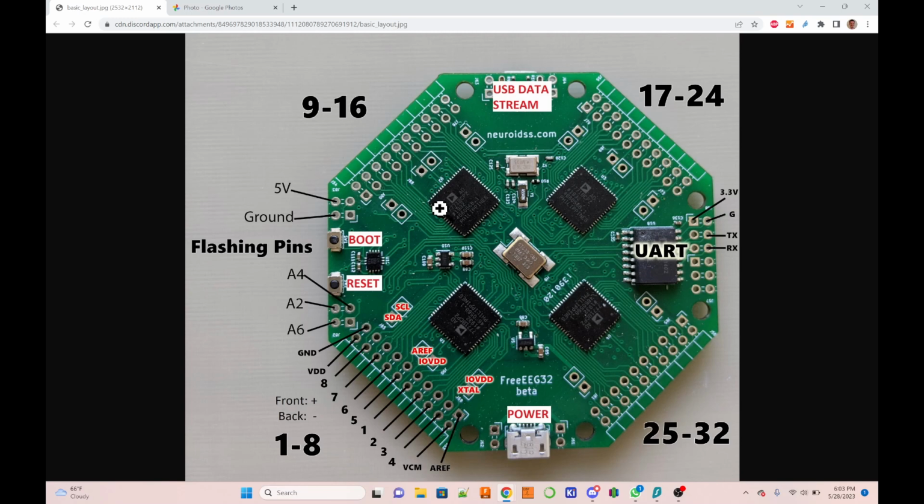In fact, if you look closely on your board, you may even see the wire that goes around the trace. So if you connect one of them, you don't have to connect the other ones on your headset. Just one of these VCM pins on your headset is enough. Of course, it is nice to just do them all four, but it's really not necessary.